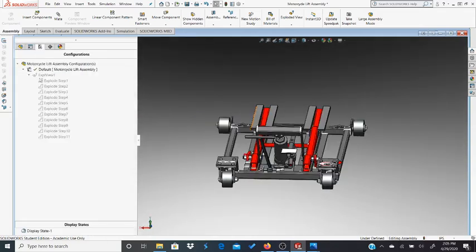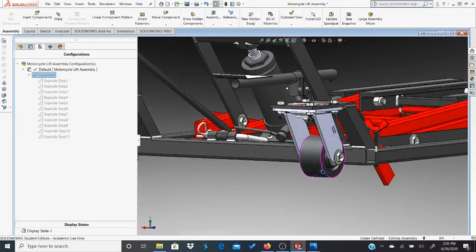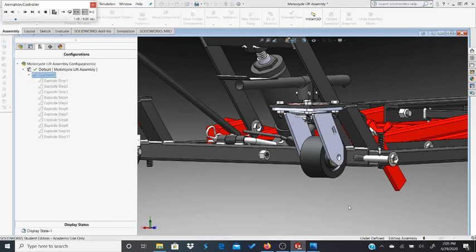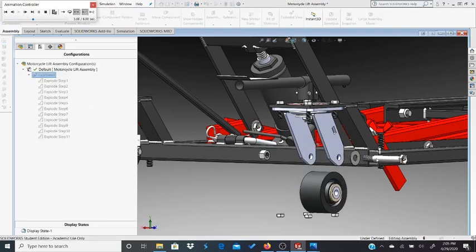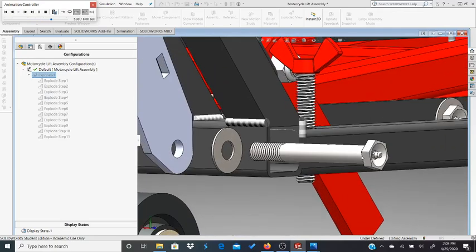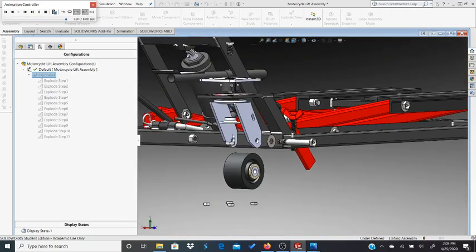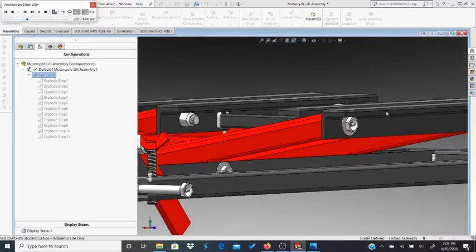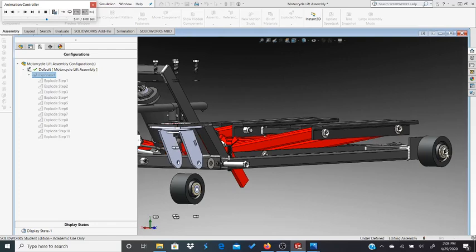Oh, so we also have a little exploded view so you can see how this swivel wheel was created. Another special thing is this bolt. You see that funny little thing at the end? That's a grease fitting. Because of how heavy this is, you want every single dynamic piece to be greased well, because otherwise it'll just wear and tear. And you can see it's on every single piece that's going to move. These are 3/4 inch bolts.